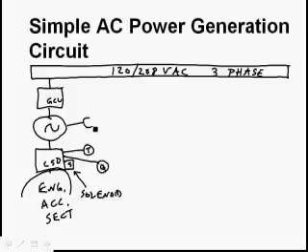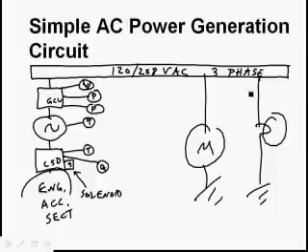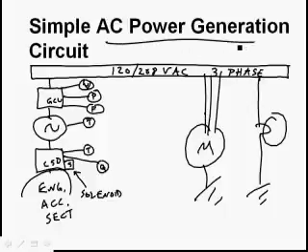We might have a temperature gauge on the generator, and of course coming off of the generator control unit, we might have a voltmeter, we might have a power meter, and we're always for sure going to have a frequency meter. And then of course we can run motors, and we can run light bulbs, and all kinds of things. And of course you'll notice I'm not drawing all the 3 wires, but in reality there's really 3 wires going here.